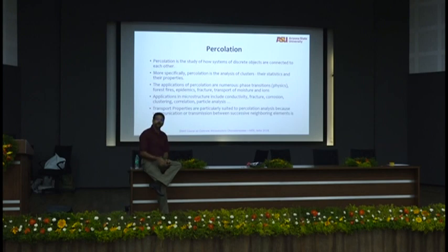And percolation is an important characteristic for any porous medium, not just concrete, but for any porous medium. And anything that you see as a contributor to deterioration of concrete starts as a percolation problem. Okay?